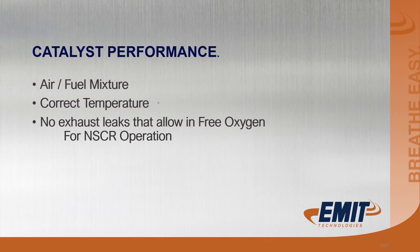For carbon monoxide, the temperature is around 450 degrees where it reaches its maximum. And for NOx, it's typically between 750 and 800 when it reaches its maximum, 850 degrees for sure. And then your other hydrocarbons that you have, or VOCs, it depends upon what that constituent is as to what temperature it takes to break that carbon chain down or break the pollutant down.